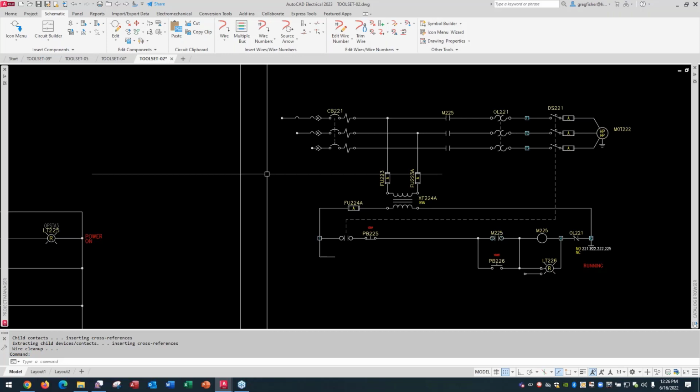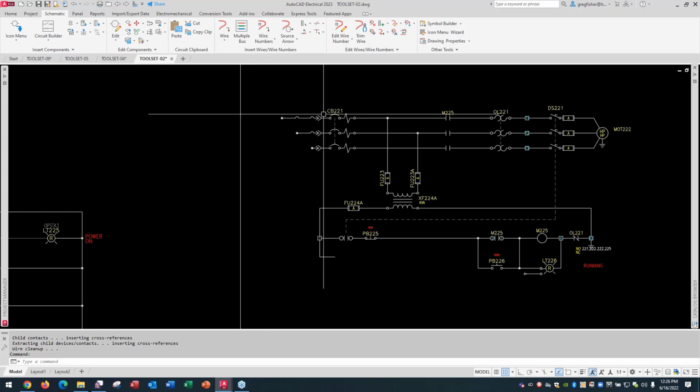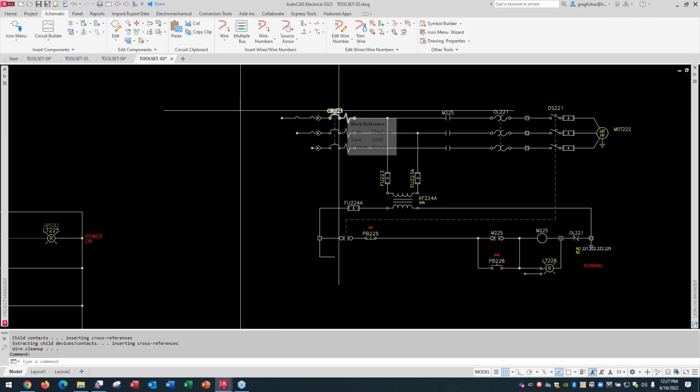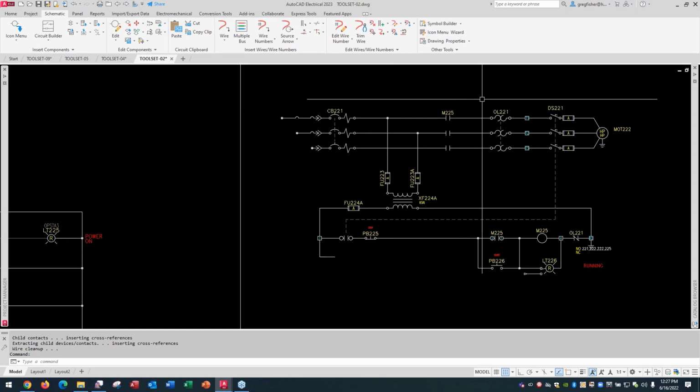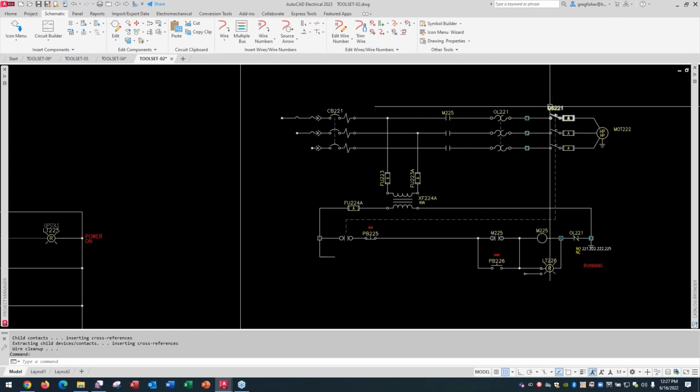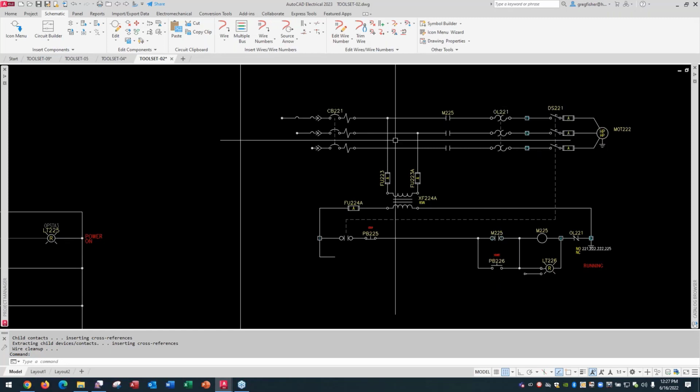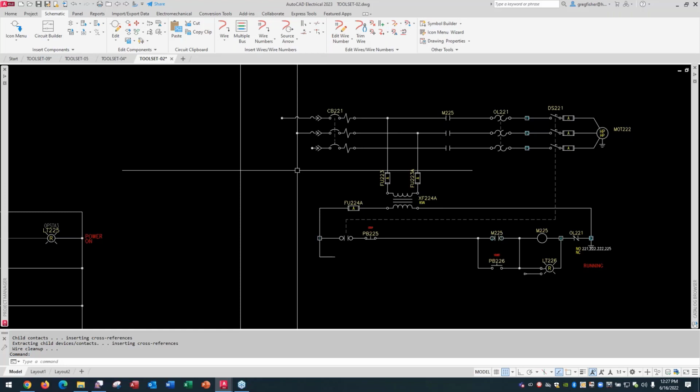It's actually saved as a block. But as part of the utility, when you do insert it, it explodes it back to its original components and wires, and it also updates the tags all at the same time. That's the power behind it. And as we recommend to people, if you think you're going to reuse a circuit, save it all day long.